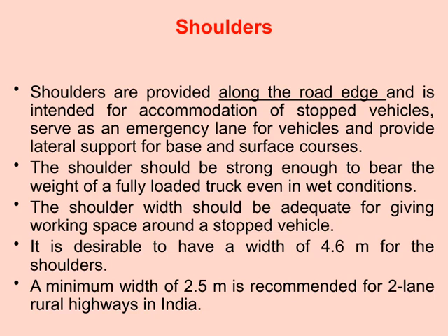Let's talk about shoulders on the road. Shoulders are provided along the edge of the road and are primarily meant to accommodate stopped vehicles. They also serve as an emergency lane, which can be very important in case of breakdowns or accidents. Additionally, shoulders provide lateral support for the base and surface courses of the roadway, helping to maintain the overall stability of the road structure.